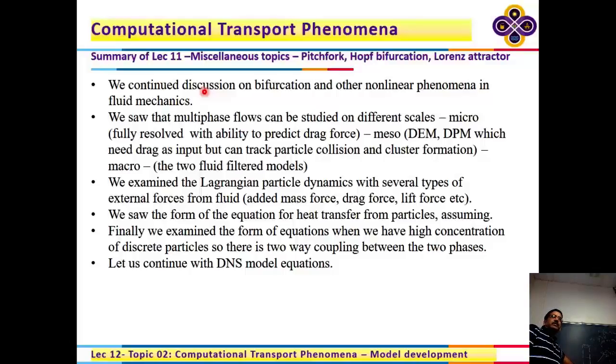Okay? Do you follow that? If you have a finite wall here, you will always have two cells near the wall. In between, you will have no velocity, but near the wall, you will be exciting both the VR component and the Z component, in addition to V theta, which is always there. The moment you have these two velocities, all these terms become alive, the terms that were dropped earlier.